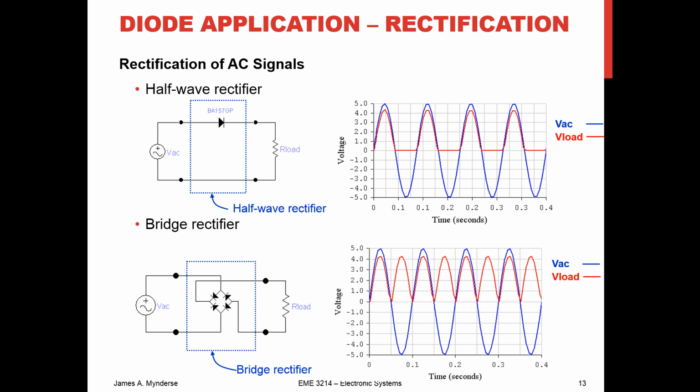If we've got an AM signal coming in, we're going to first fold it up and then we're going to average it, and that'll give us our AM signal. Well, demodulated signal. But that's rectification, half wave and full wave rectification. We'll need these for various sensors.